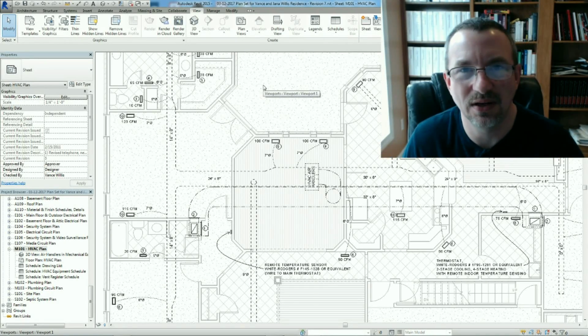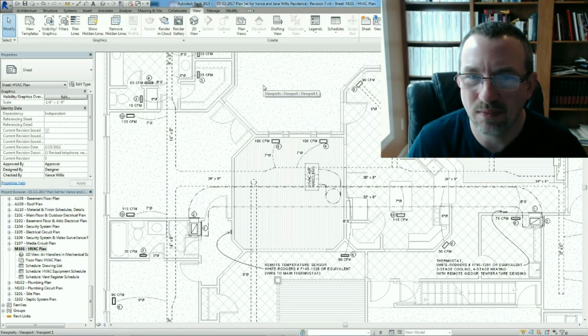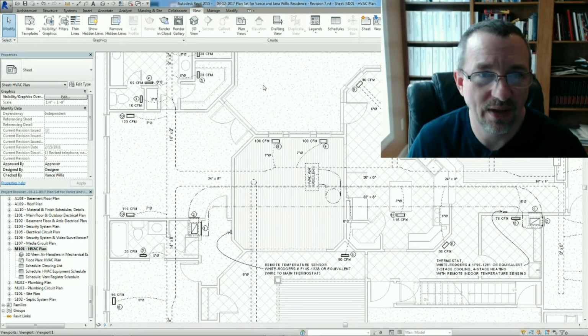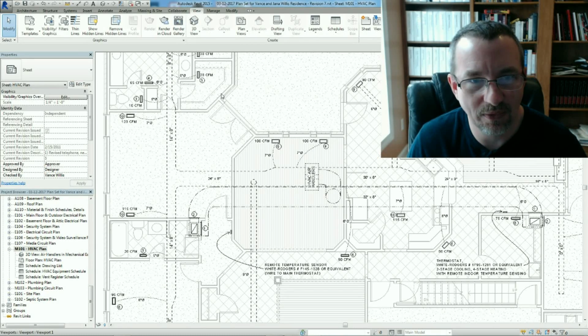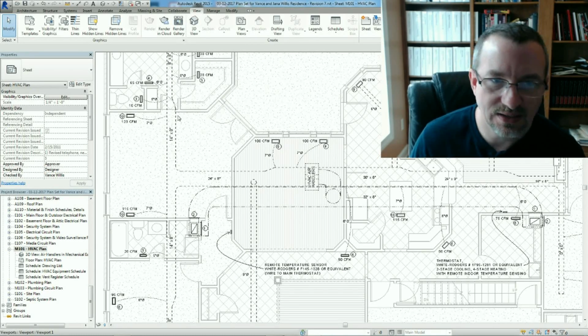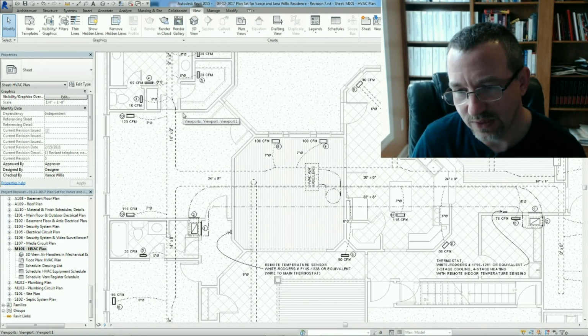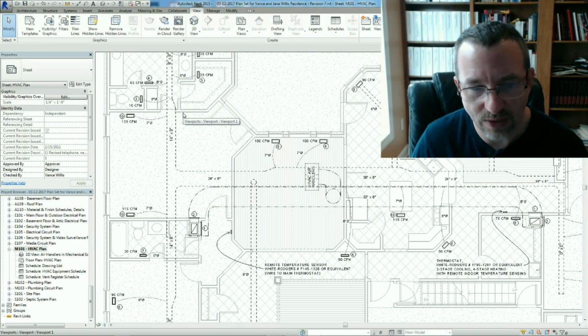It can be pretty complicated, but it ended up being a really massive spreadsheet that I'm not going to bore everybody with trying to show you all that. But I did that, and that's where I came up with all the CFM to all the different rooms. So that's how I sized all the trunks. That's how I sized all the flex lines and the registers and everything.